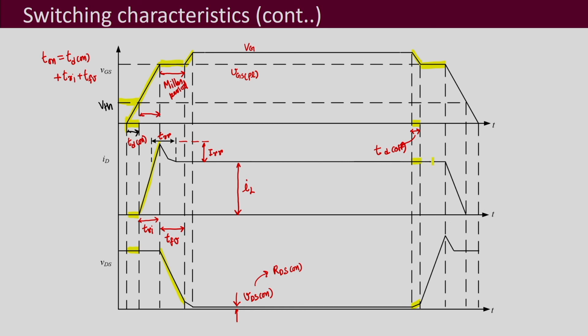Further, this Miller period continues, and at that time what we observe is that the current does not change, it remains where it is, but the voltage builds up. The voltage builds up and there is a shoot through in the voltage. It goes above what it is supposed to block. So, there is a rise in the voltage and almost no change in the current.